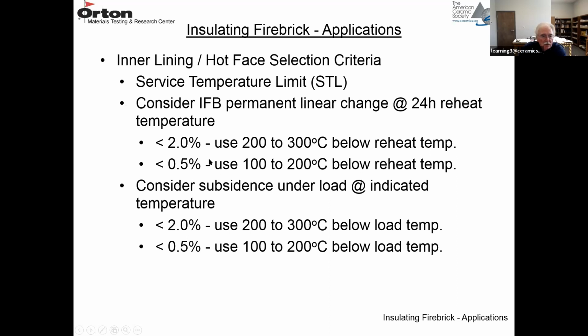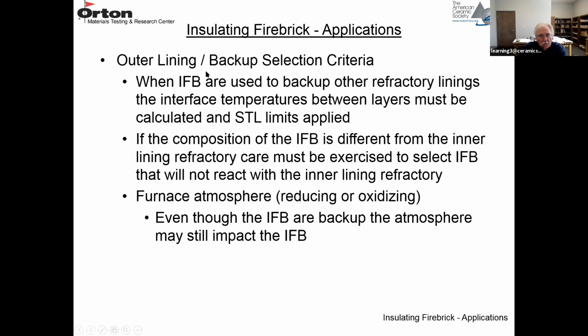So these numbers here, these different percentages give you an idea of what temperature you should be able to use the IFBs at for the outer lining. So you can use the IFBs as an inner lining as long as it's a furnace that is not containing a slag or a glass or corrosive atmosphere or mechanical issues. You can also use it as a backup in any of the other situations.